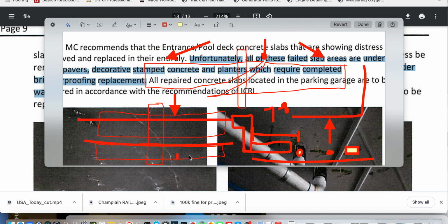And so now I can make this huge recommendation, if you will, that we need to replace this deck because the core sample and my visual of the hole are showing that this is splitting apart. This is what I theorize. And now this deflection would look like this, and that's why we would get the gap. You would see the bar. Let's put the bar in here like this. Now there's the bar. Now you see the gap.